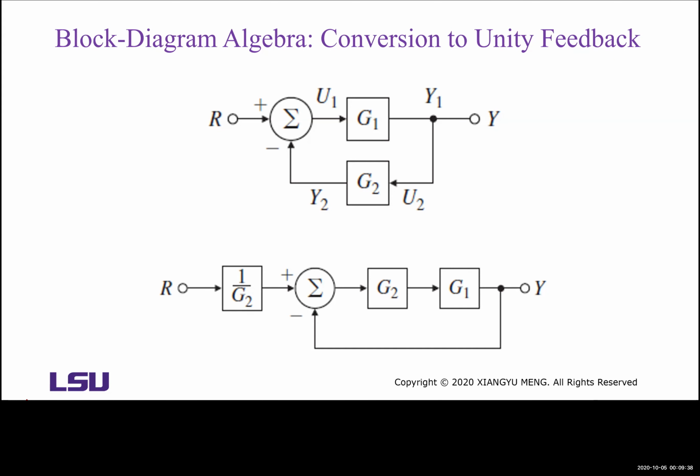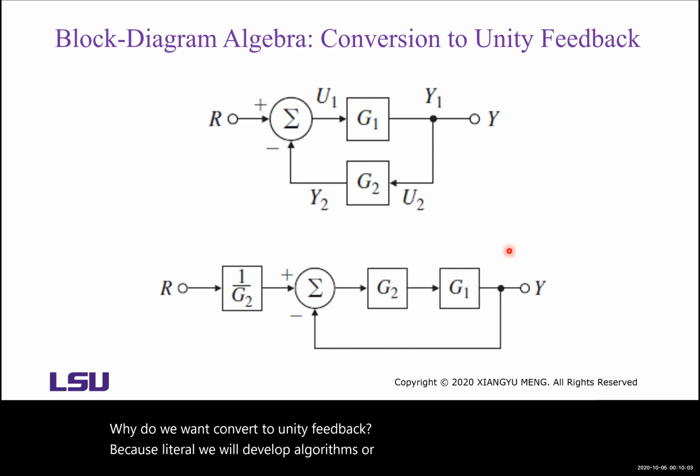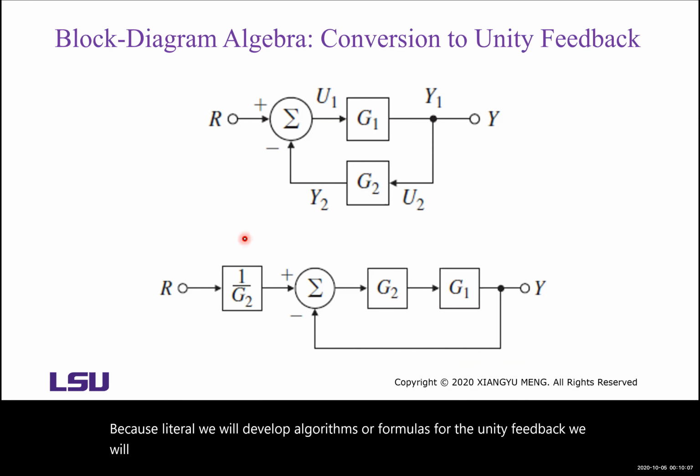So that's the block diagram algebra converting to unity feedback. Why do we want to convert to unity feedback? Because later on, we will develop algorithms or formulas for the unity feedback. We will consider the unity feedback as the standard of the negative feedback.